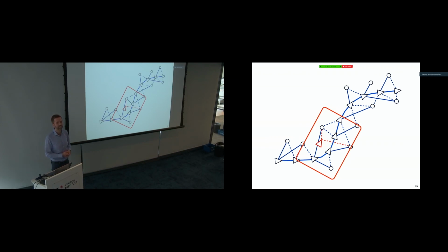Normally, if we're doing a more classical technique for state estimation, like the Kalman filter, you end up having to take the gradient of your motion and observation models with respect to the state in order to pose it as an optimization problem, so that you can figure out what the state is.